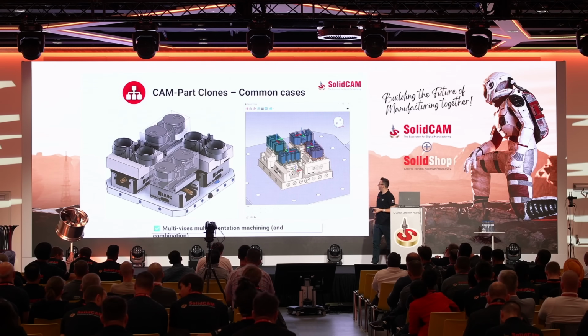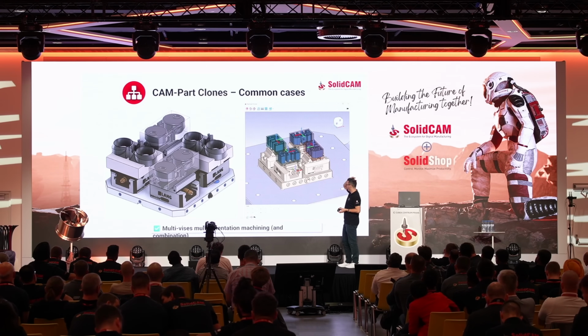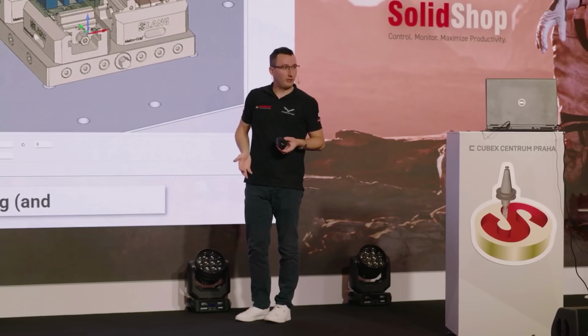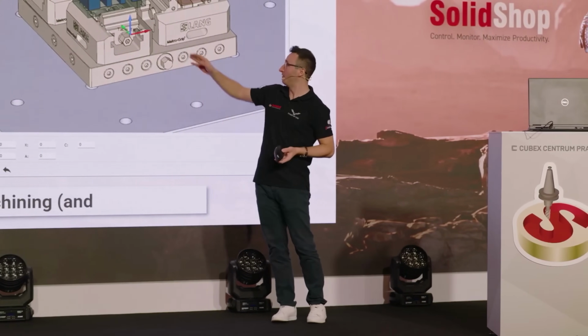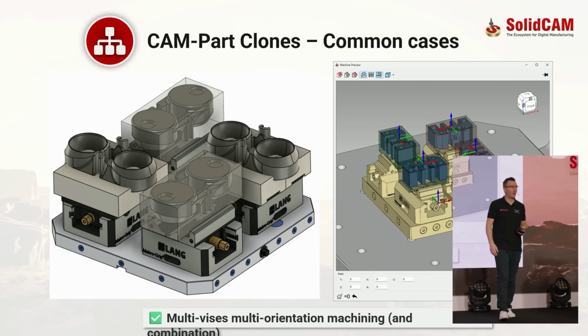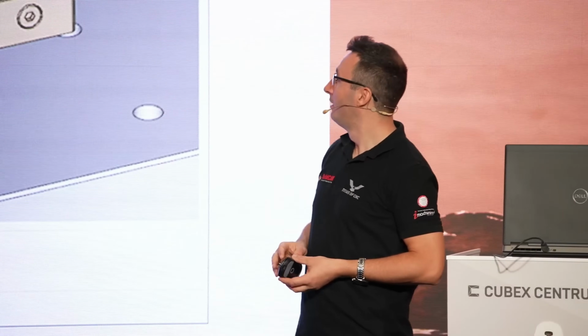So over here, this is the same example, but what is interesting to mention here is that these 4 parts are completely different orientations. So they are saying it's the same G-code. No, this is not the same G-code. You can have even different X position, Y position, Z position. You can think about that these Ys can be rotated 45 degrees. The toolpath is the same in this case, yeah, sure, but the output can be completely different. So that far we went. Let's go next.